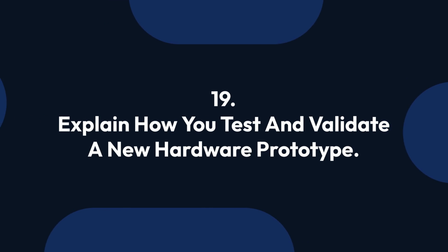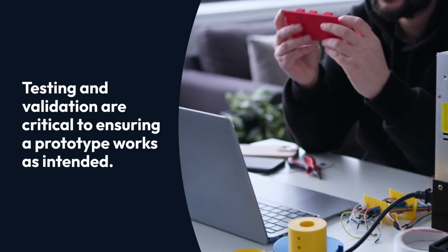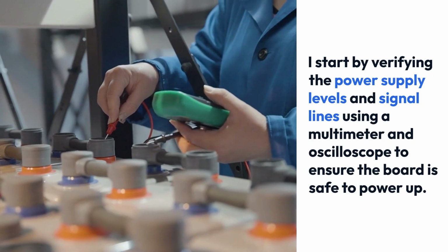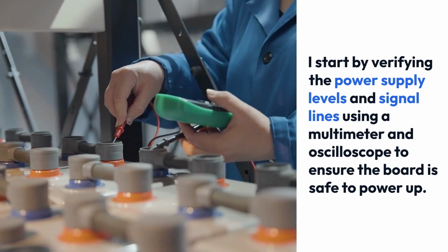19. Explain how you test and validate a new hardware prototype. Testing and validation are critical to ensuring a prototype works as intended. I start by verifying the power supply levels and signal lines using a multimeter and oscilloscope to ensure the board is safe to power up.